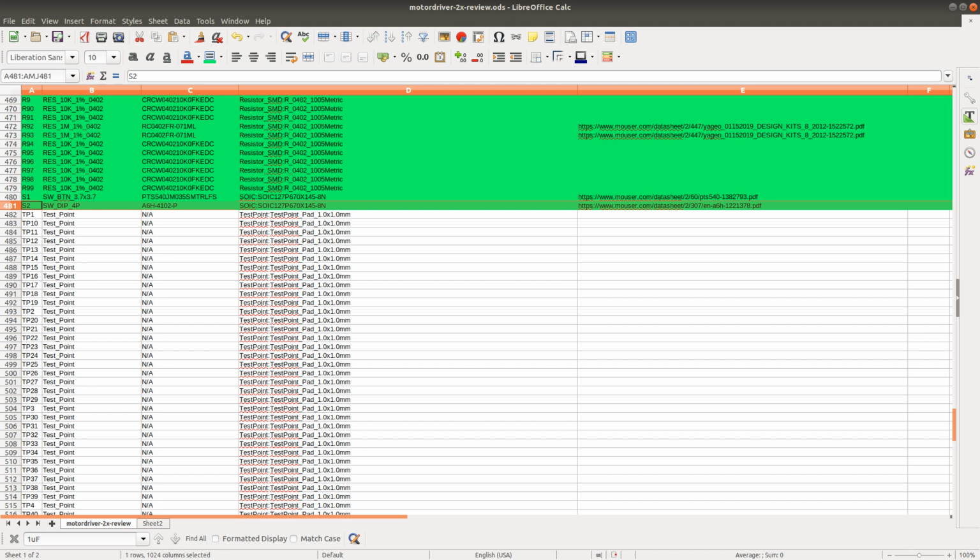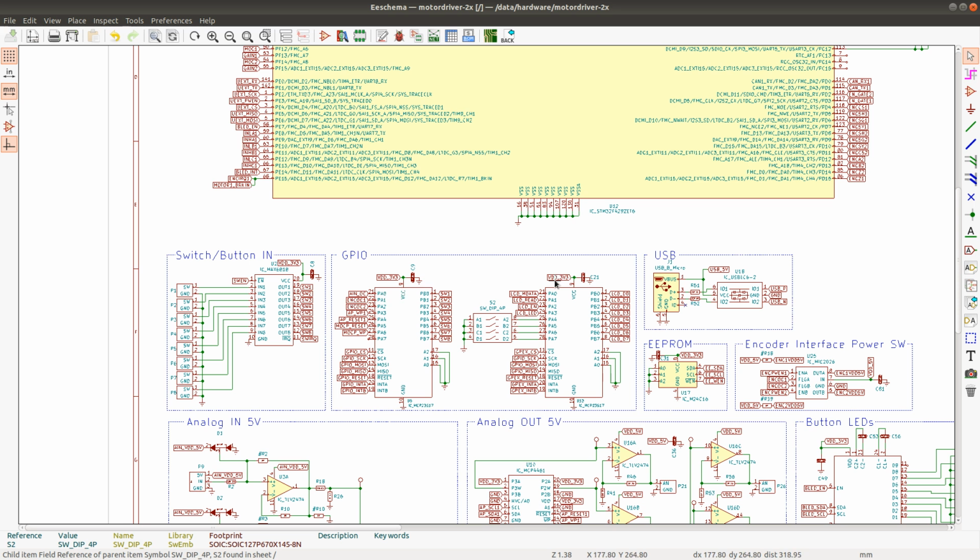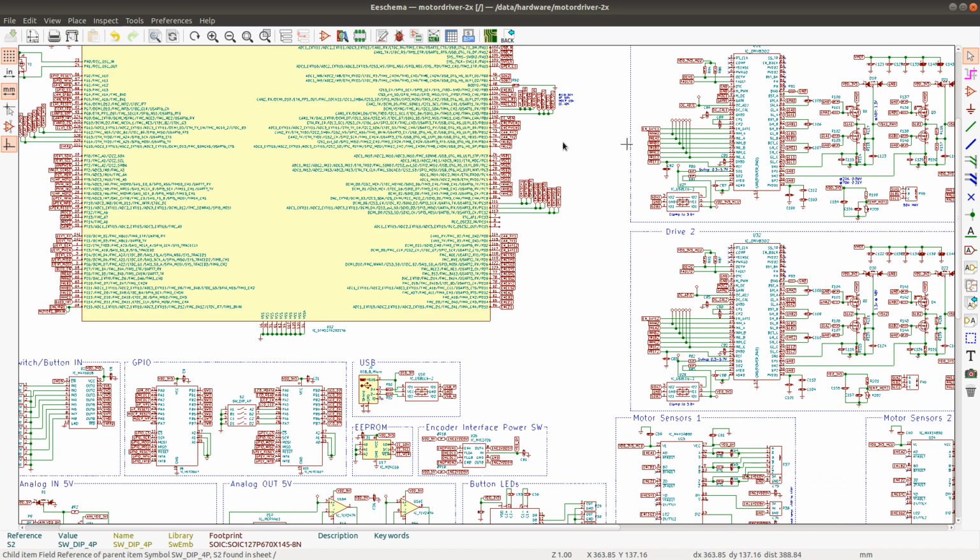And then all of the test points. I'm going to go over the test points that I have in the schematic right now, and then I'll see if I can find any other places where I have to place test points. Actually, with regards to free pins on the microcontroller, I'm going to place test points on them, because then I can use those pins to output a direct GPIO signal in order to debug things like timings, interrupt latencies, and things like that. I usually use the LED that is connected to the STM32 to do that kind of thing, but it's also nice to have more than one pin to be able to see the timings between different things.